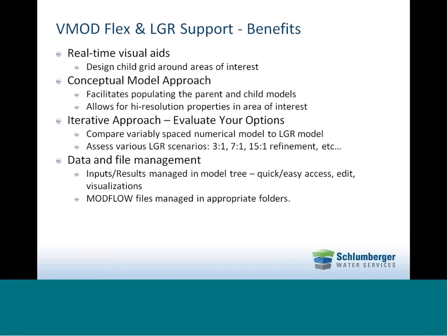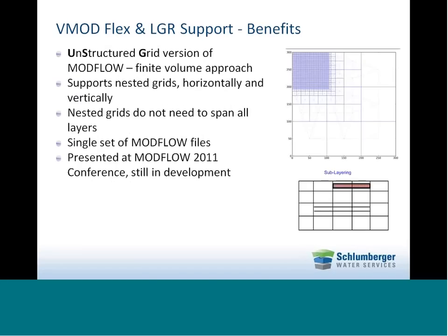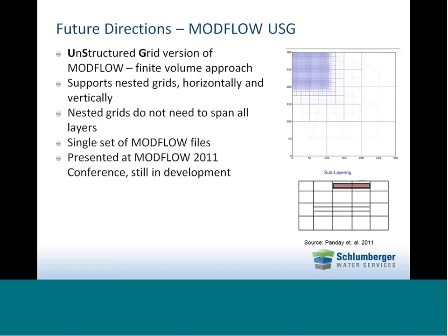And lastly, as I mentioned, you're dealing with several Modflow files, cells, and calculated results for both the parent and the child grid, and we offer efficient means for managing the data objects and the files within VModFlex. These include both the input parameters, whether they be constant head cells or river cells for the parent or the child grids, and connectivities for the parent and the child grids. You can easily access and edit these from the model tree. And then when we do the translation to Modflow, these are managed in appropriate folders on your hard drive or whatnot. So that's an overview of Modflow LGR. We'll go into the demonstration shortly.